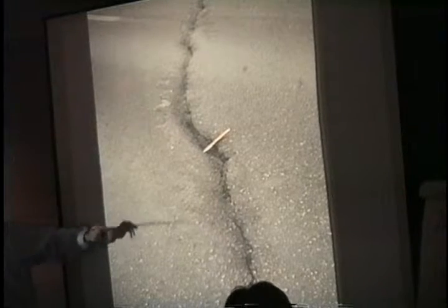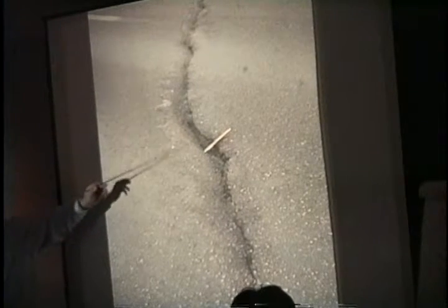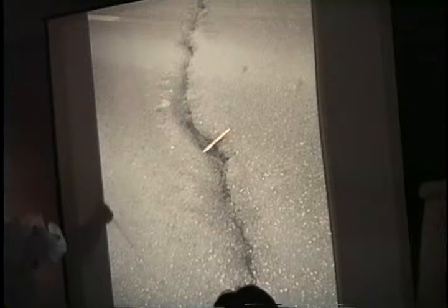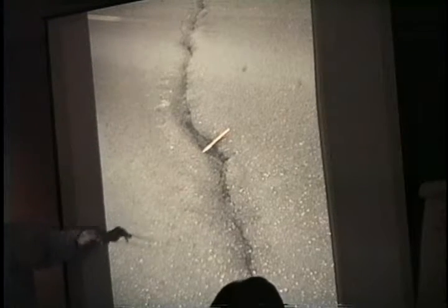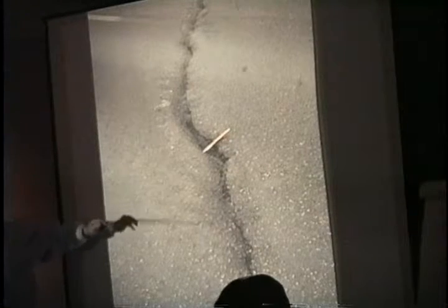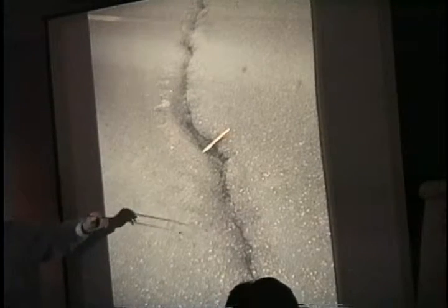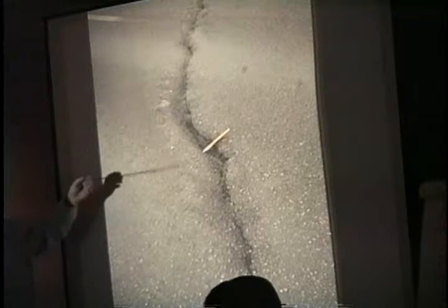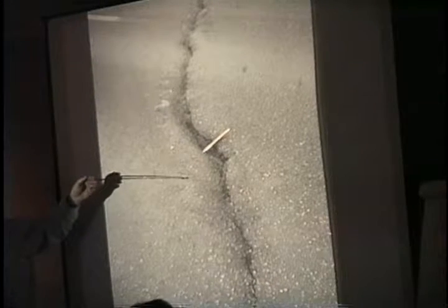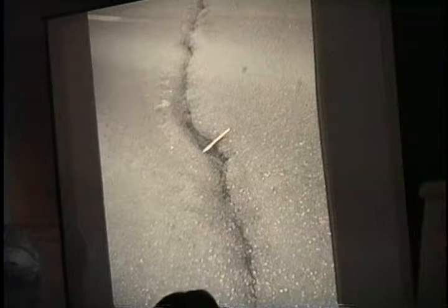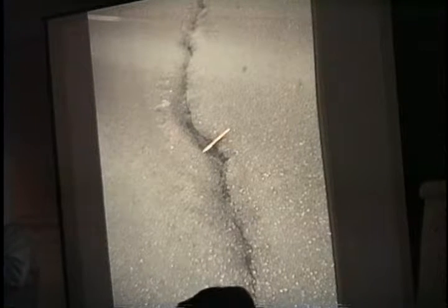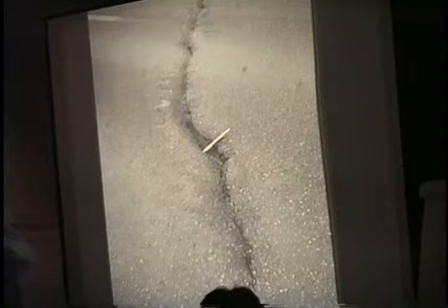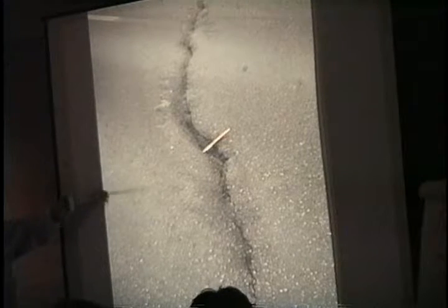We could seal this crack. I agree with you, road safety is important. You've got to level it up. If this is clay, you might even inject a lot of lime or lime fly ash in that tension crack, because that'll help to strengthen the shearing resistance right in that slide plane. Just another little trick I learned over the years.